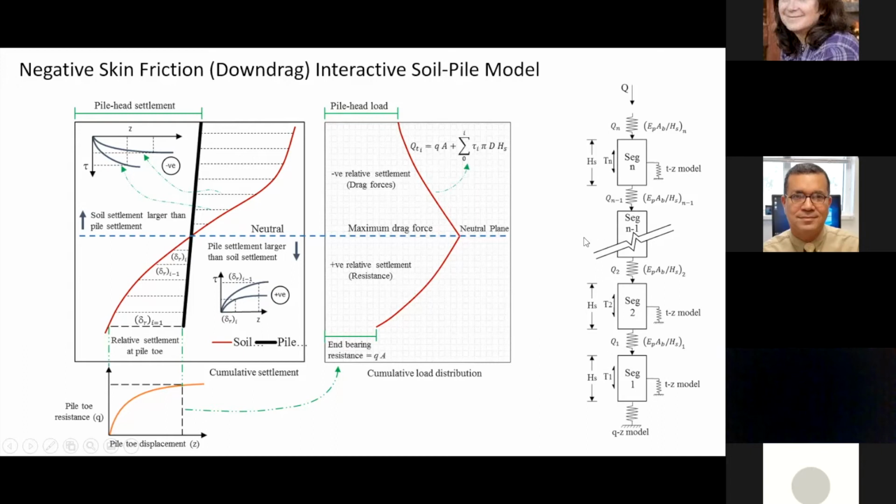When we solve the axial loaded pile, in fact, we do not solve from the top to the bottom. We solve from the tip to the top. So we start with the segment at the tip here, starting in an incremental fashion. So we analyze the pile with the soil in an incremental fashion. What do I mean by incremental fashion here? I start loading the pile gradually with small values and then increase this value gradually until I capture the balance I'm looking for. For example, here we start with segment 1, assuming that we have a very, very small level of loading, and then we move from one segment to another to study the balance with the surrounding soil until we reach the top.